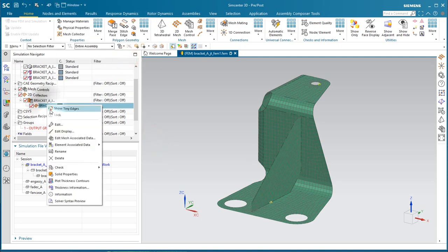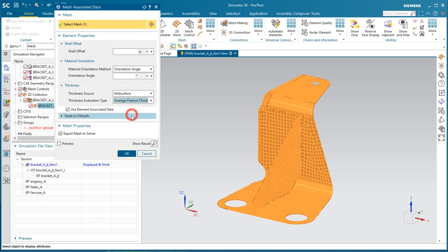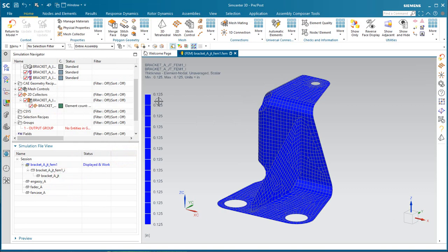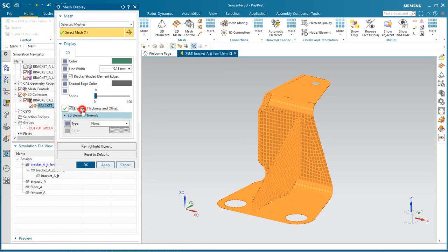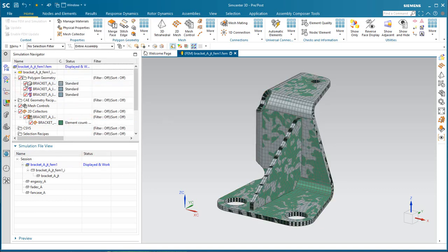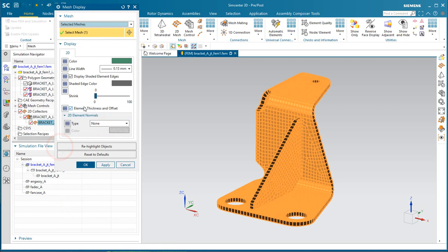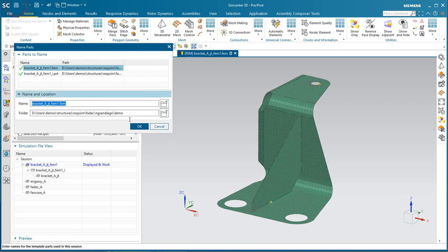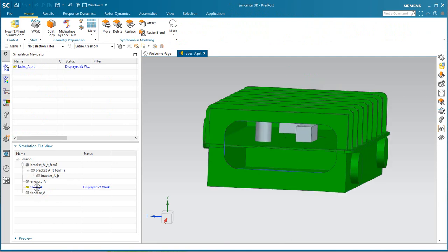All right, so we did not specify material. We also did not specify a mid-surface thickness, which we can inherit from the mid-surface. That way it reduces or eliminates another source of error in assigning a thickness to the shell mesh. Here you can see we can display that either as a contour or as a 3D thickness, and we can compare that to our solid representation of the bracket as well to ensure that we've got the thickness inherited correctly. So both thickness and material can be inherited and were for the bracket definition.